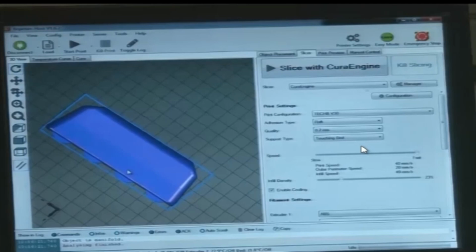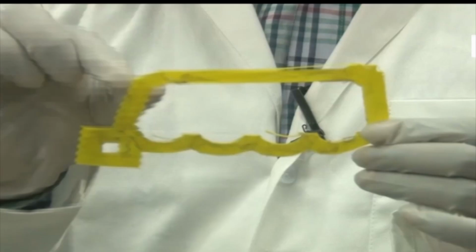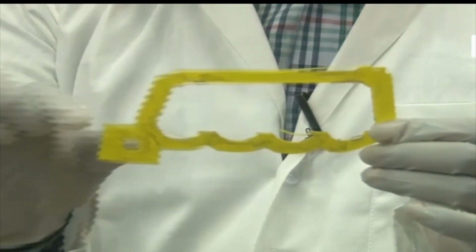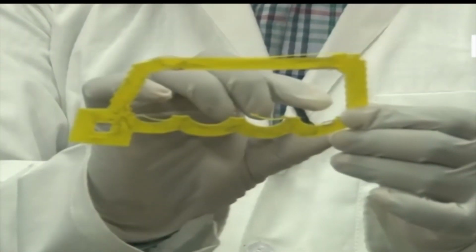So this is brim that is taken off from the job that is prefabricated. This is the model that will be developed. This is the pocket. This extra material is brim. This whole material is brim. So this is taken off from the project that was manufactured before. This will stick with the bed properly, and this enlarged area, this is the first layer, will provide a good holding with the bed.